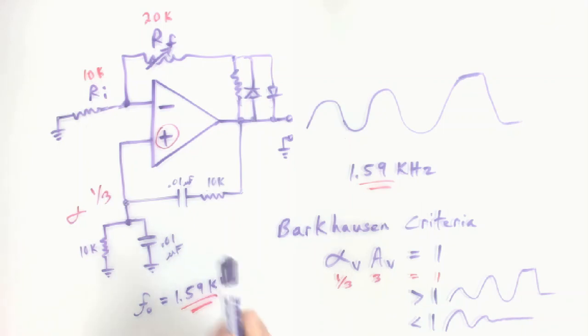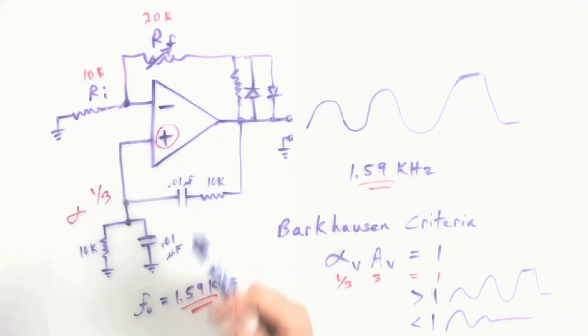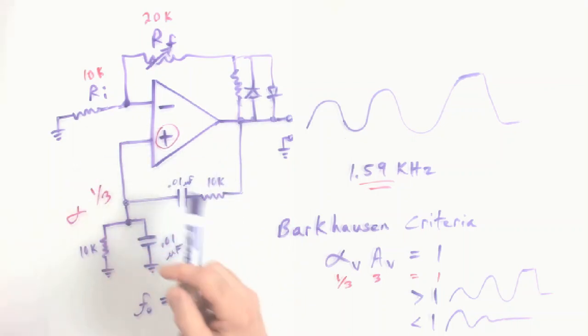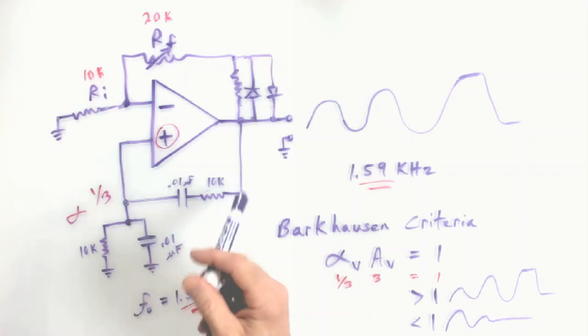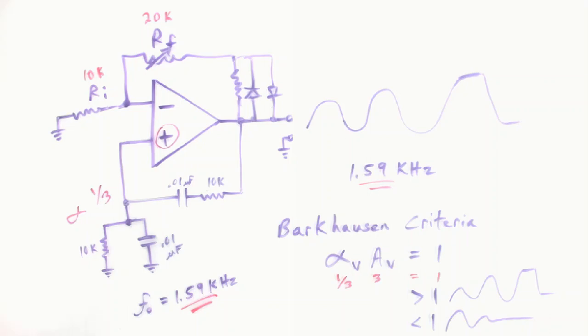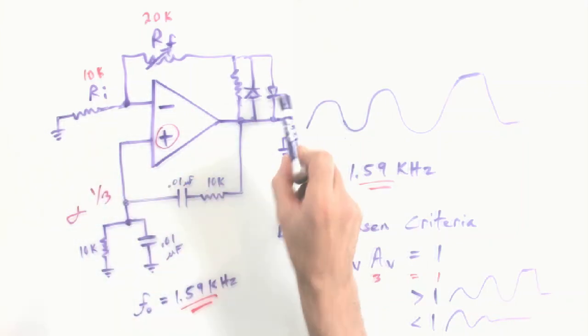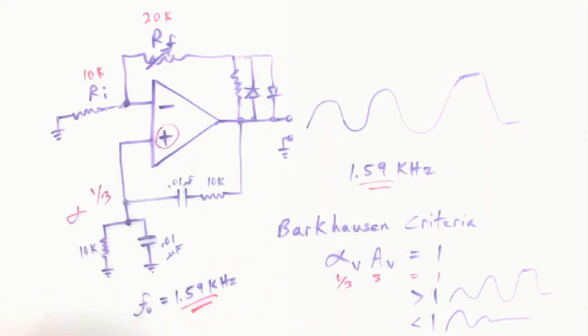And I don't know that we have diodes. If you have any laying around, you can do this too. But those are all optional type exercises, the self-regulation of gain. You can play with it if you have time, or you can try to dial it in carefully, but you'll see how touchy it is. But with either one of those, the lamp that Hewlett Packard used or this, you can get a very stable and very low distortion sine wave once you take care of that gain regulation.